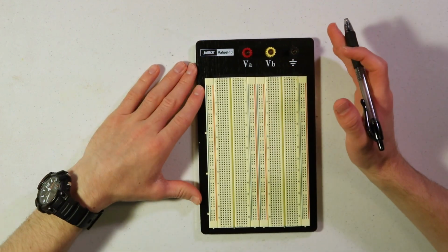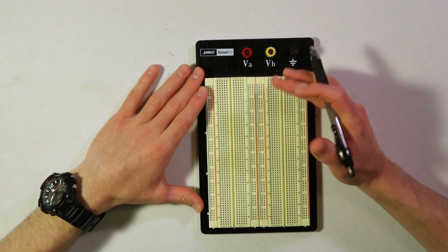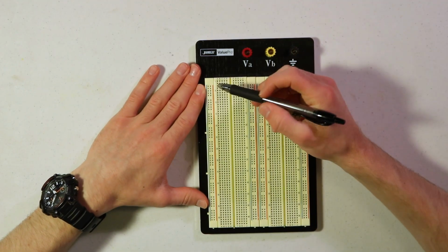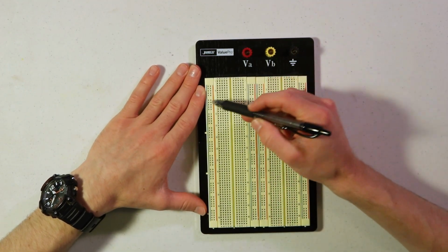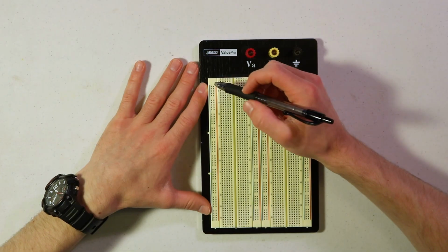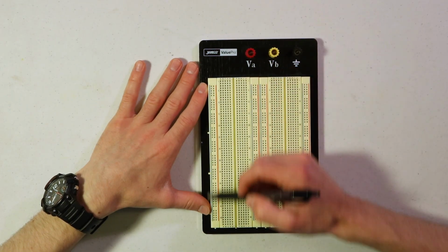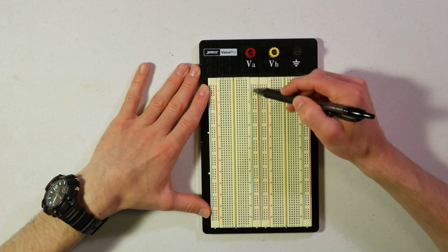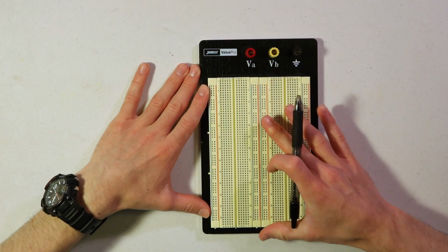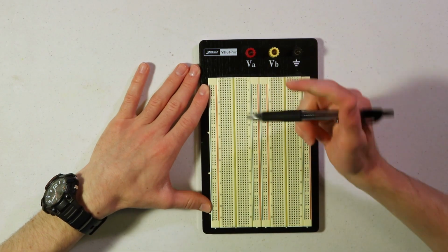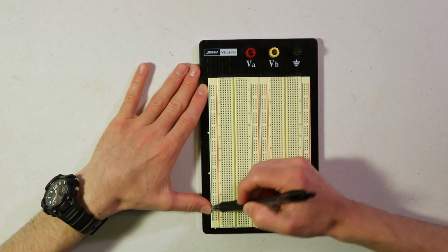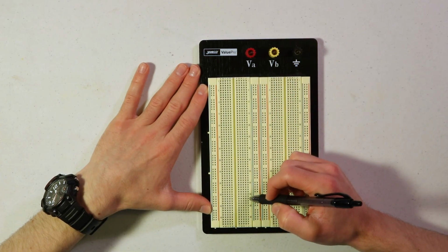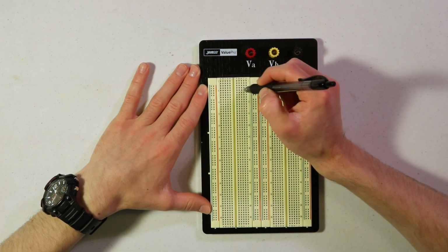Now there's often a lot of confusion about how these breadboards are wired up, but it's actually fairly simple. You just need to understand the 2 main areas that we have, which are the power rails and then the rows. So for each breadboard we have 2 power rails. We have the red and blue line on this side and then the red and blue line on this side. And in my case I've got double that, but for you, you would just have the red and blue lines here and then the red and blue lines here. And then in the middle are the rows.